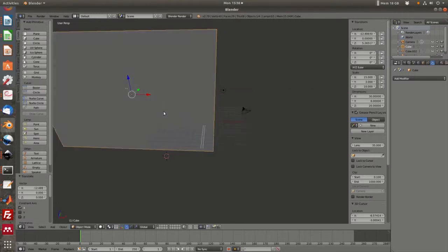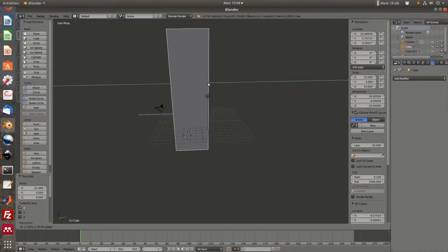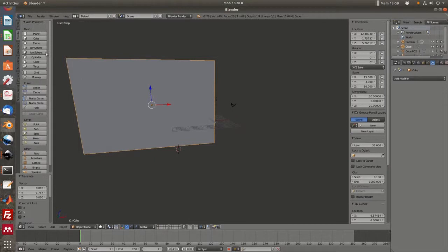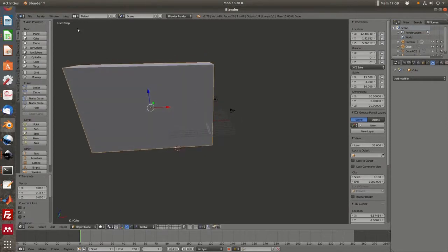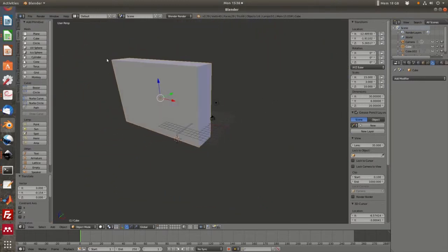So now we need to reposition the tissue so that it's in the positive quadrant in Blender, so that when we export it, it's in the right coordinate system for the PDE toolbox. So we just need to move it towards the positive quadrant, and we can leave a slight overlap in each dimension with the negative quadrants because we've created a tissue block that's a bit bigger than our actual tissue.